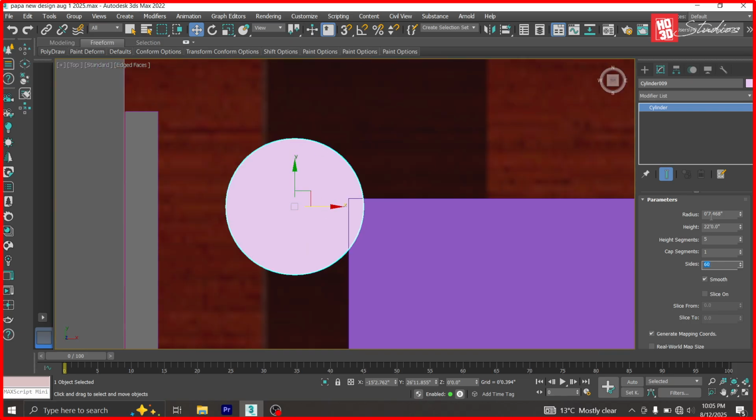So that's okay. Now, the diameter of the pipe, which is quite common in Nigeria for water towers, is 3 inches. So 3 inches would be 0.25 feet. That's a quarter of a foot, because a foot is 12 inches. So now here we have the radius.